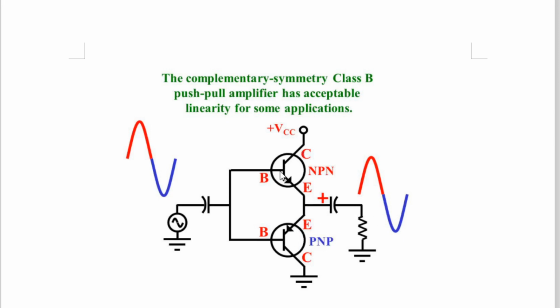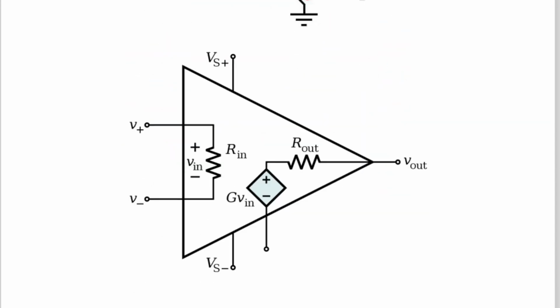And in this way, these two transistors combining together will work as an amplifier in the last block of the operational amplifier IC. And this is the final output of IC741, that is pin number 6. Now after understanding all these blocks, there is the equivalent circuit diagram of the OpAmp. What is the equivalent circuit diagram?